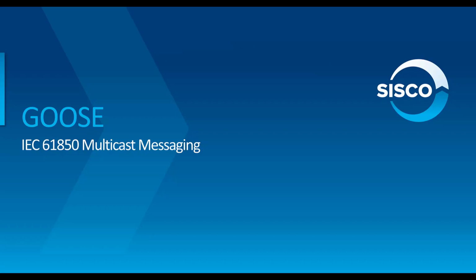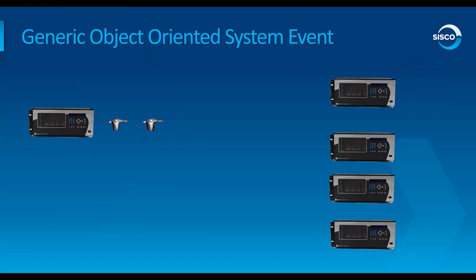IEC 61850 GOOSE messages are used to send event data between devices in the power system. These GOOSE messages are Ethernet multicast frames, or in the case of the newer routable GOOSE, UDP multicast frames. Multicast means a device can send one message and have it duplicated out to any number of receivers or subscribers.